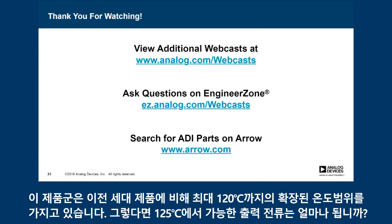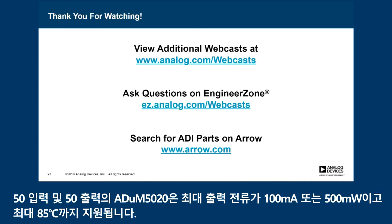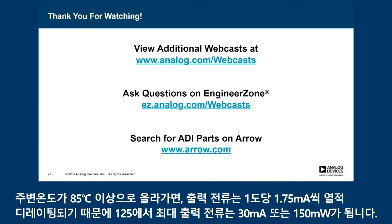This one asks, this family has an expanded temperature range of up to 125 C compared to earlier generations. So what's the available output current at 125 C? The ADuM5020 at a 5-volt input and 5-volt output has a max output current of 100 milliamps or 500 milliwatts up to 85 degrees C. As the ambient temperature rises above 85 C, there's a thermal derating of that output current of 1.75 milliamps per degree, so that at 125, the max output current is 30 milliamps or 150 milliwatts.